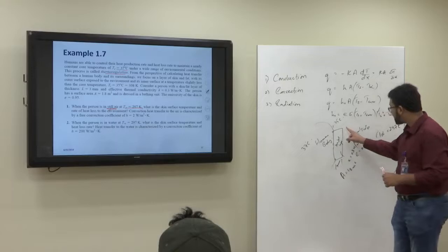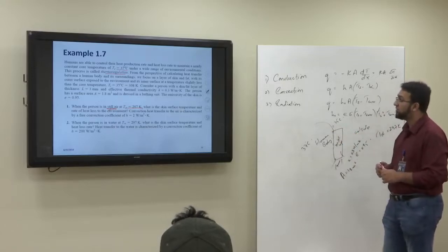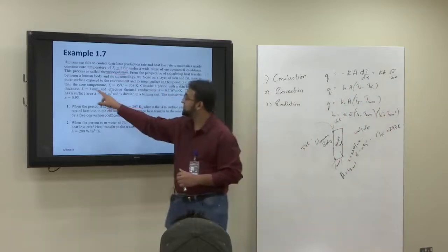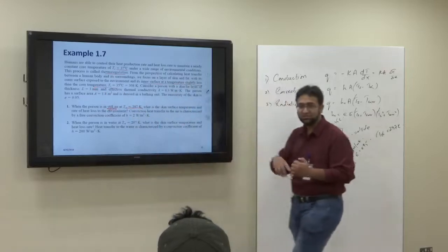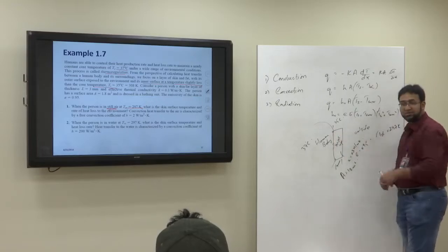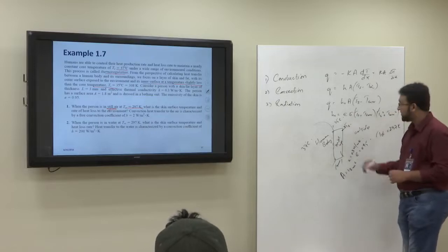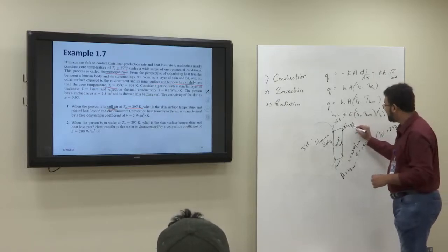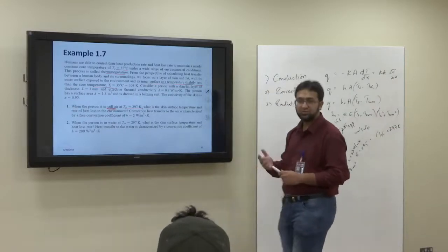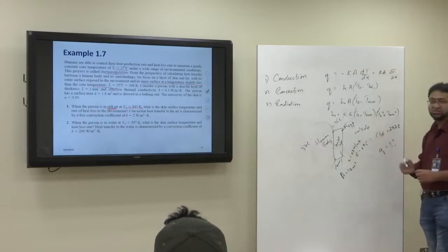We know the temperature just below the skin. We know that temperature, its inner temperature at the surface slightly less than the core temperature. So that's the inner temperature. Okay, so skin fat layer inside temperature is 35 degrees centigrade. We don't know what is the skin temperature. So this is what we need to find out. Determine the skin temperature and the rate of heat loss. Rate of heat loss means Q. So we need to find Q and we need to find Ts.